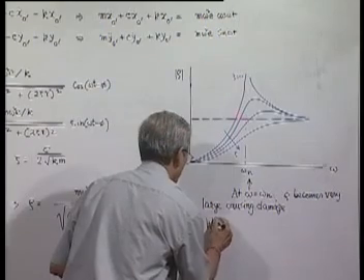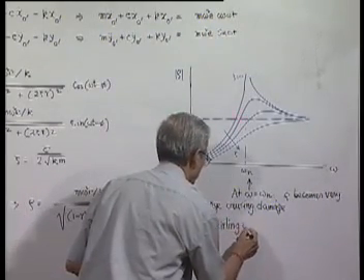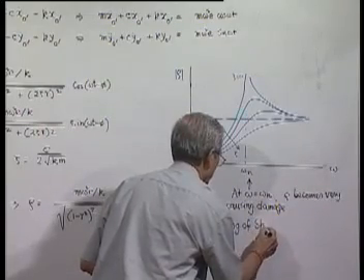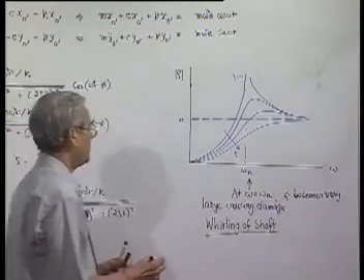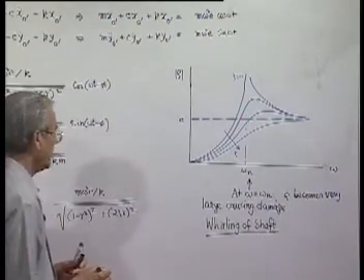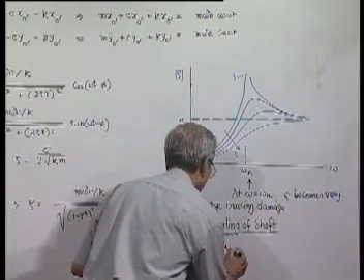This phenomenon is called whirling of shaft. It is the simplest possible case of forward synchronous precession, and the speed at which it happens is called the critical speed.